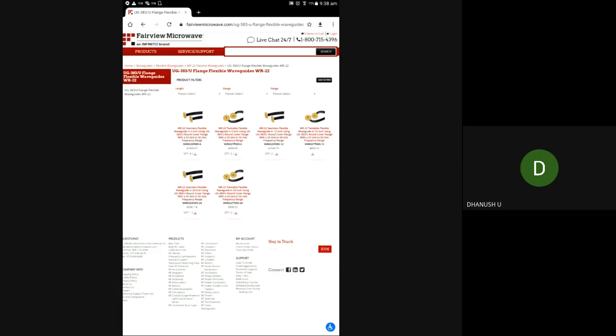But this pipe kind of structure can handle more power. That is the main point I want to tell you: the key significance of the waveguide is that it can handle more power. And still we are not in this range to design high frequency RF circuits. Maybe they are proposing a terahertz oscillator, terahertz LNA, terahertz PLL, but integrating them and proper impedance matching still has a lot of difficulties.